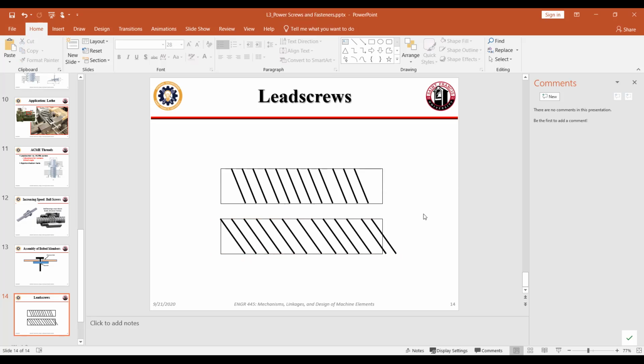So if I have my regular 3/8 12 screw, it means I have 12 threads per inch. Or if I invert that, it's 1 inch per 12 threads, right? If I work out the math, 1 inch divided by 12 threads, that means I have 0.083 inches per thread. So if I turn my nut once, I'm advancing that nut by 1 thread, and I go forward 0.083 inches.